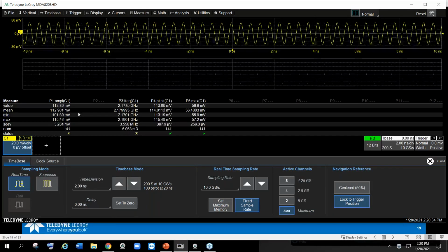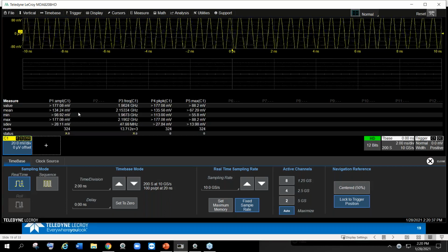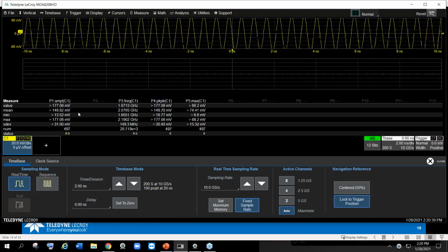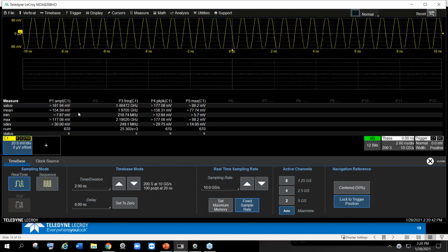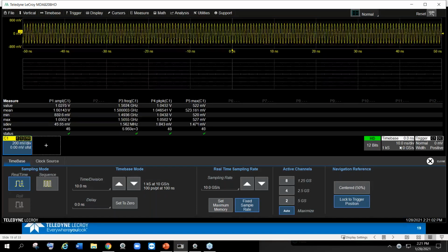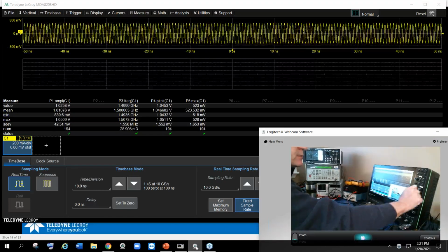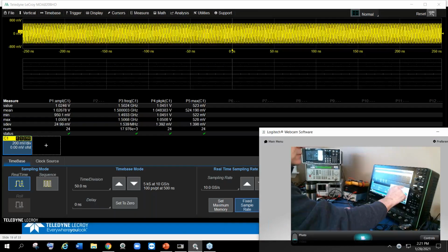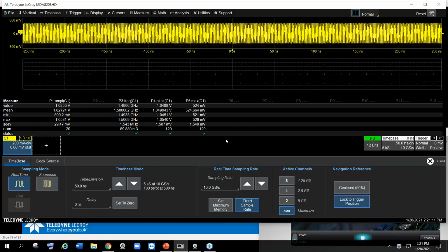For example, I am right now, let's clear sweeps. I'm at 2.1 gig. Let's just drop it down to 1.5. Clear the sweeps. Of course, I changed the sensitivity. Okay, now we have a good signal. So if I want a wider time window, we're going to vary that. And so that's 10 gigasamples. We're using 5,000 waveform sample points.